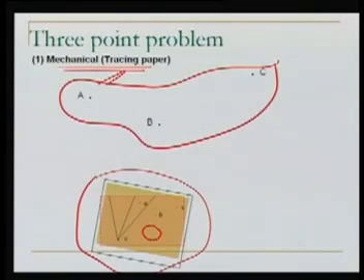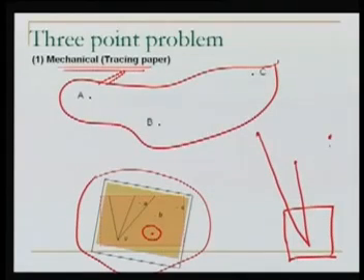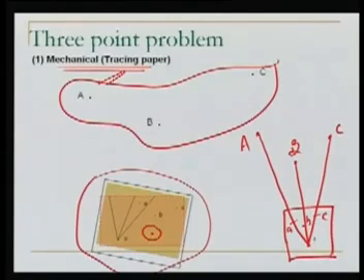Okay, so on my sheet I should be somewhere here, and if my actual location is this, as we know, if my plane table is oriented corresponding to A, B, and C, I have small a, small b, and small c, and that's the point P where I am. Now this angle is alpha, this angle is beta.